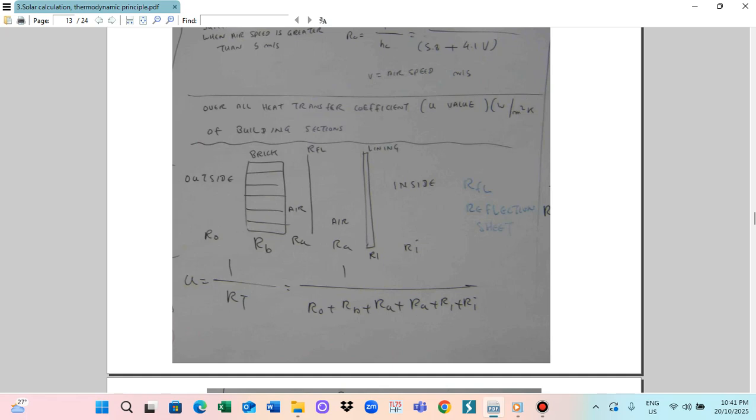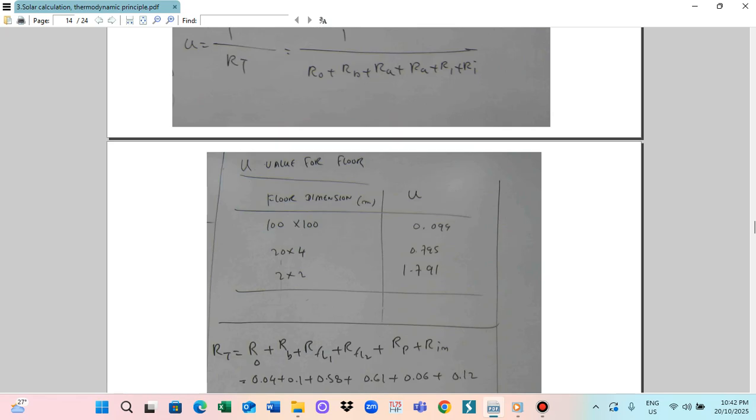So resistance, this is the R. This is R. This is R. And this is the R. So R value depending on the construction. If your wall is a wall construction, this way you can take the R value here. And this is for the roof R value and also surface resistance R value. So how the roof is constructed, you check it and you find the appropriate R value from the table and you substitute.